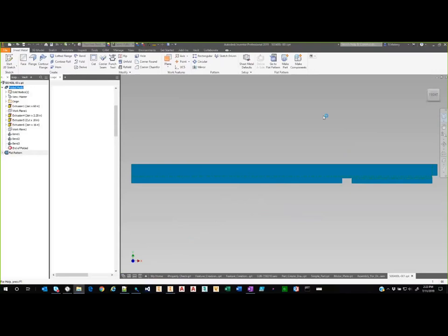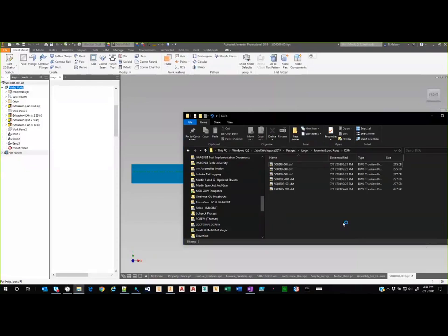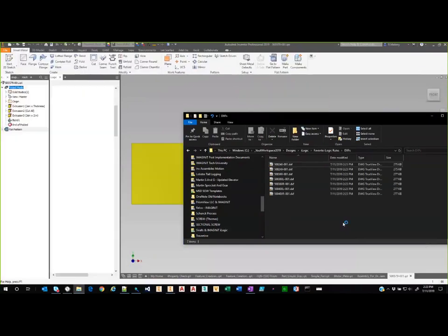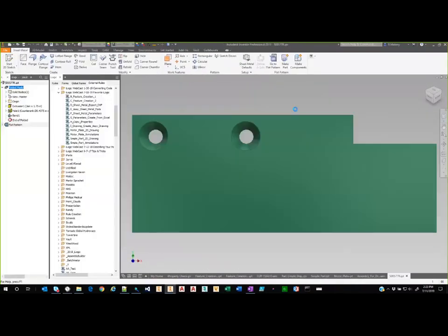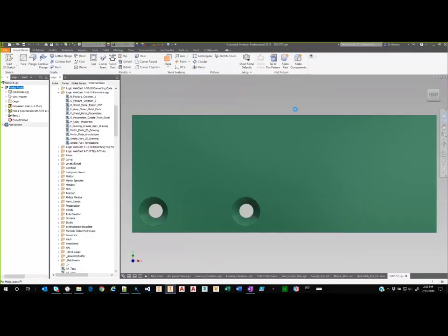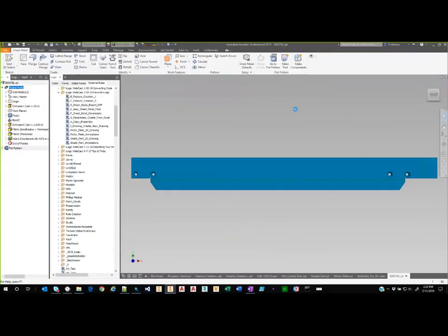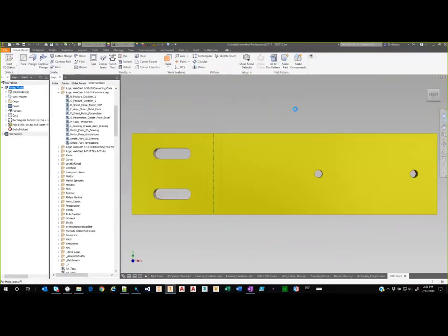So here is, let me pull that over. I'm throwing all these into a specific folder here. So you can see those DXF files starting to populate and build inside of that folder. In this case, there's also some duplications of some components. Some of those parts might be used in multiple places. I've got a check in there. I'm keeping a running array of all the parts that I've processed. So if a part's in there 10 times, it's only going to process it once. The next time it comes across it, it's just going to skip it.